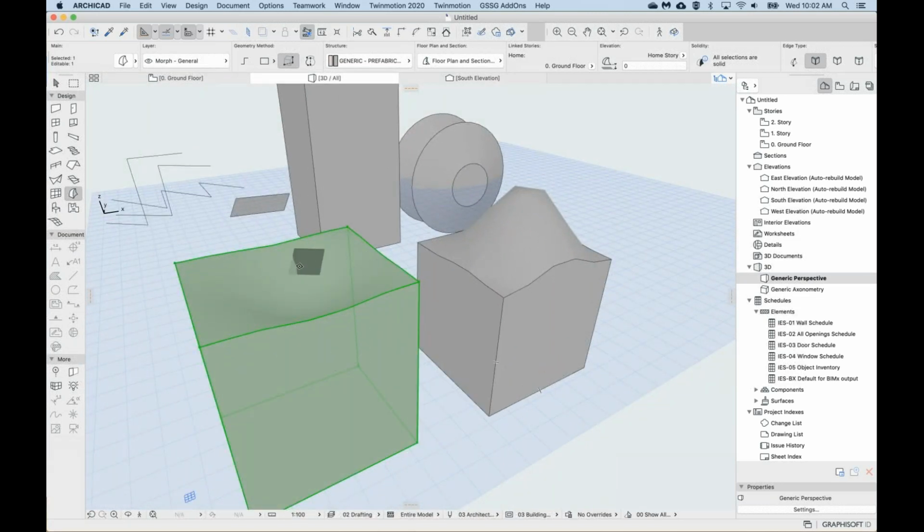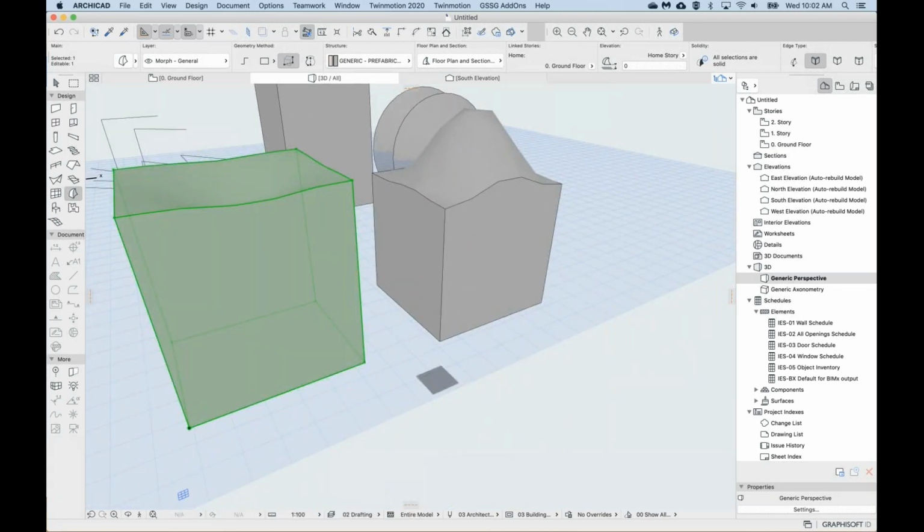Again, the bulge is not something that I can change parametrically, so I can't just modify the radius or modify the deflection. So once it's created, it's created. I can start distorting it, but it's more freeform. So how did you go with the bulge command?